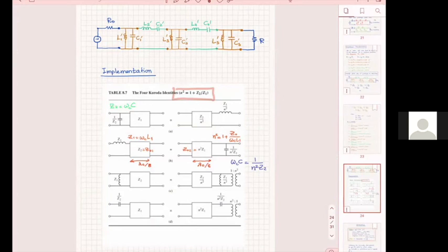You're going to see how the filter performs. I don't need anything in between. So the power at the load as a function of frequency divided by the power at the source. Yeah, you take the ratio, so it's a plain number, but I would normalize it practically, and then you find the power at the load, and then you plot it over frequency.